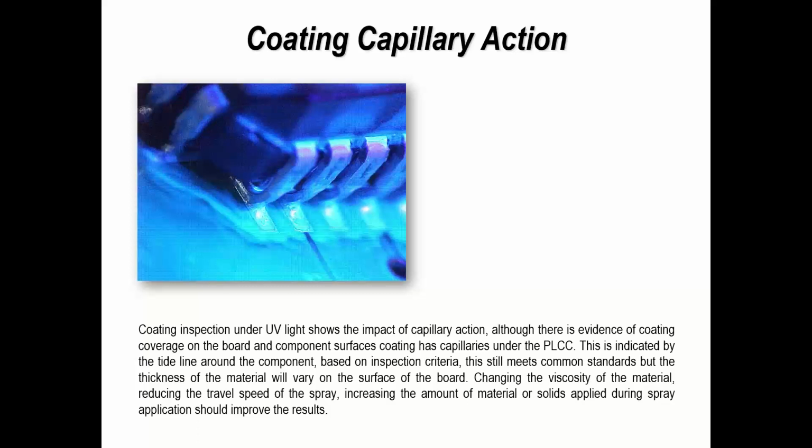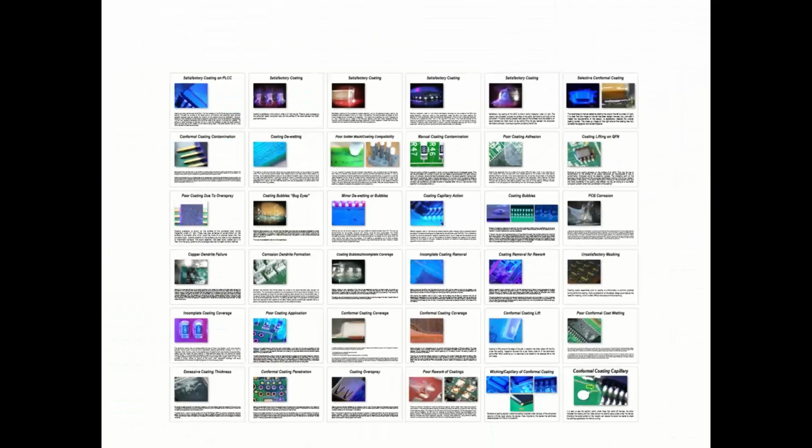So again, personally, I don't think it's a real issue. You could just do another coating run on the board and overcome the visual issue, but that's why it's happening. It's capillarying, and if you video it, as I've done in the past, you can actually see it happening prior to finishing the coating process and then going into curing.